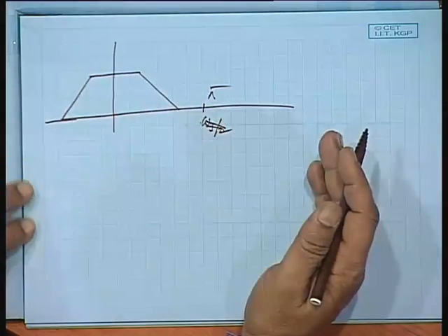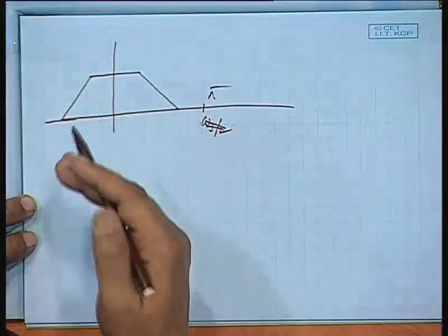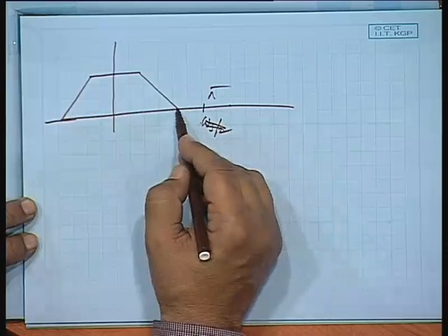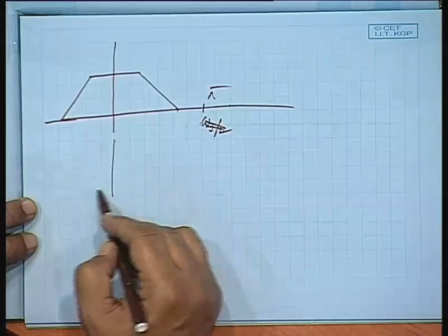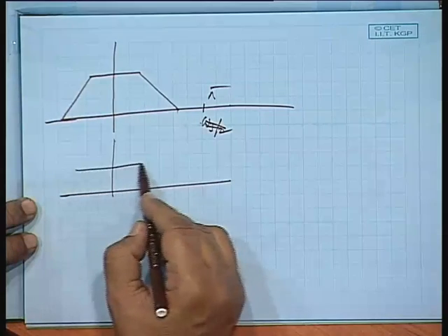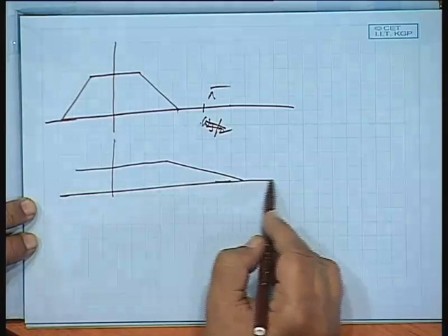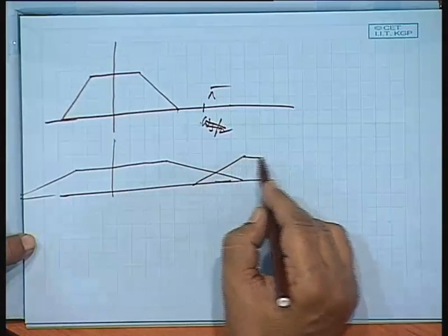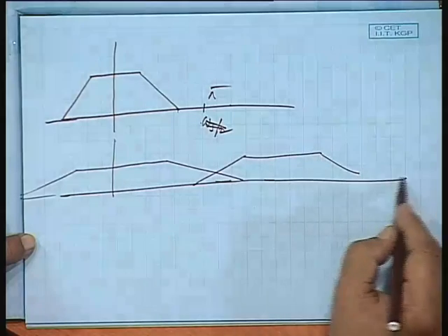Suppose I have downsampled it by a factor of 2, that means the frequency is doubled. So, this will be going into this, okay, it will be doubled. So, the base will be expanding like this, and then there will be aliasing.